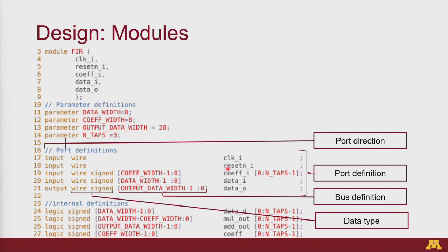One more follow-up question, I just missed that. When you mentioned, like the question I asked, if I want to declare another module with tabs number 5, I would need a different module, right? No, you use the same module, you just override the parameter when you instantiate it. Could you provide an example? I don't think I have an example of how to override parameters, but maybe I can just point it out in the one where I show instantiation.